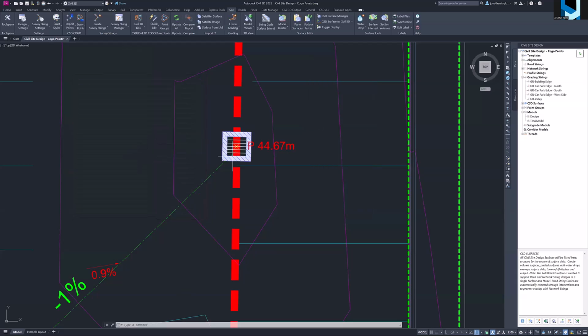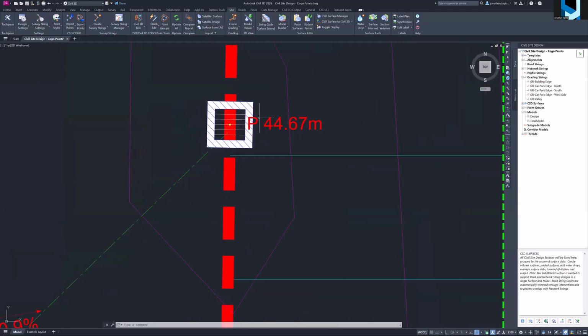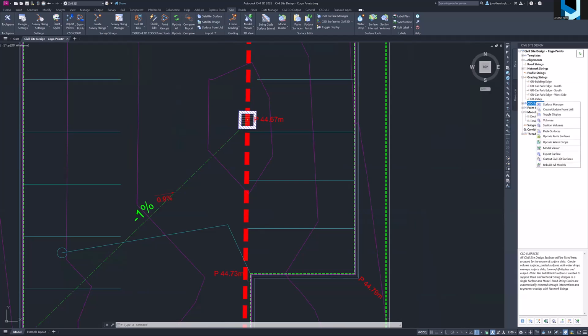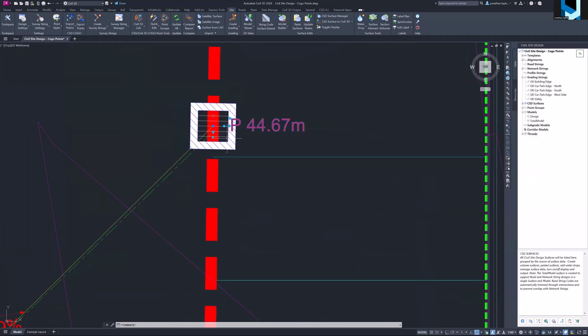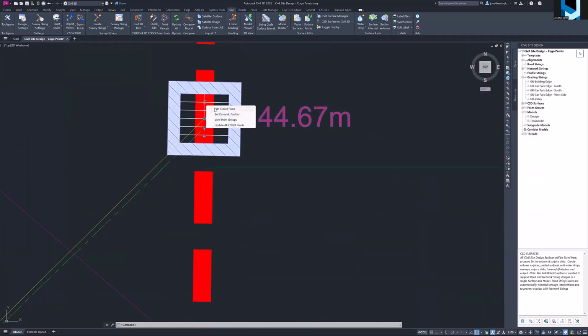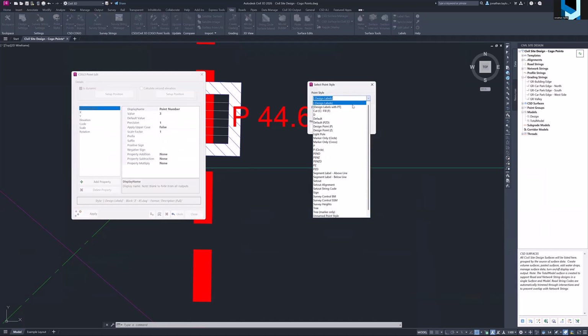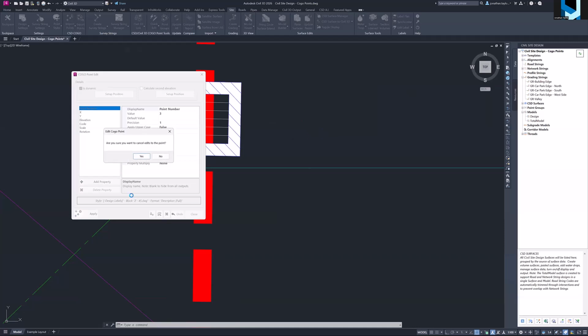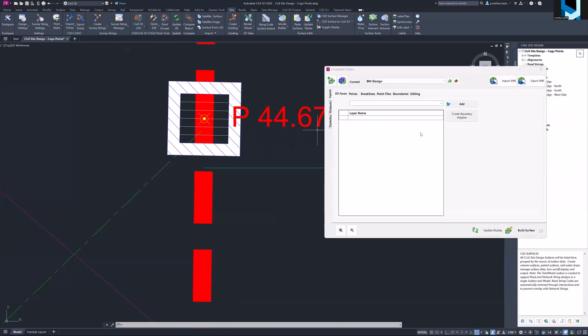Yep. Now, you'll need to delete the CAD point, okay? But fortunately, it doesn't come back again. So if I go back to Surface Manager now, because I've changed the style, let's go build. You see it's gone. Let's just pop that back in again, just to show you the process. Hover, edit Cogo, replace style. Yes, I want to replace the style, and I want it to be design with point. Apply. Yep. There we go. Back in again. Let's head back to Surface Manager. Right click. And we'll just click build. Don't need to do anything. The layer still exists there.